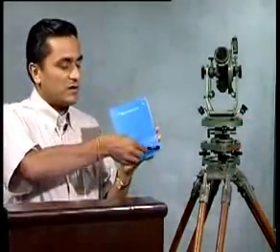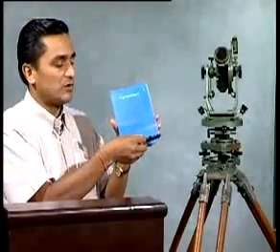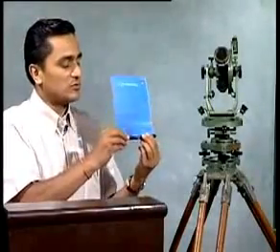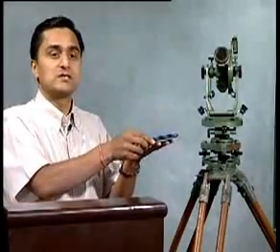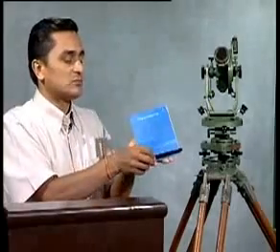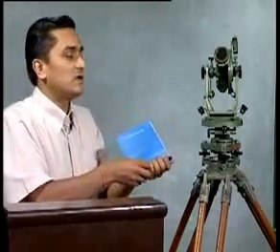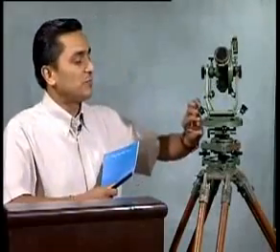Okay. Now there may be a case, for example, just think here. In this case, if this black pen is the bubble tube, right now the bubble tube is horizontal. But how about this plane? This plane is not horizontal. This plane will be horizontal only in this case. So there may be cases when the bubble tube is in center, as right now I see, but we are not sure whether the plate is horizontal or not. So we have to follow a particular step, a particular strategy, in order to ensure that this is horizontal.